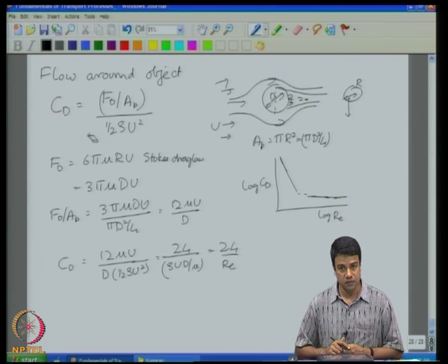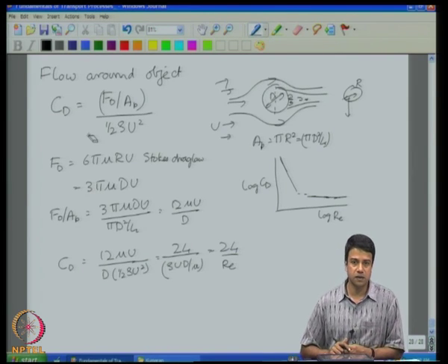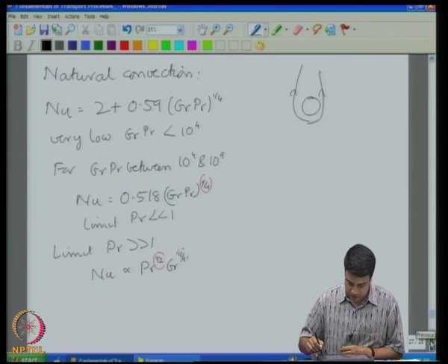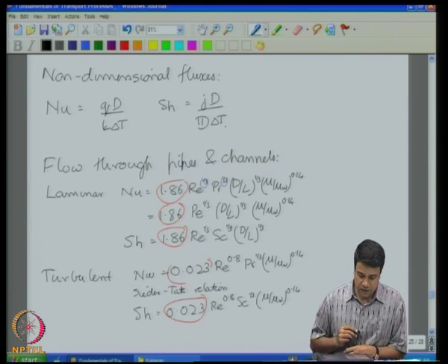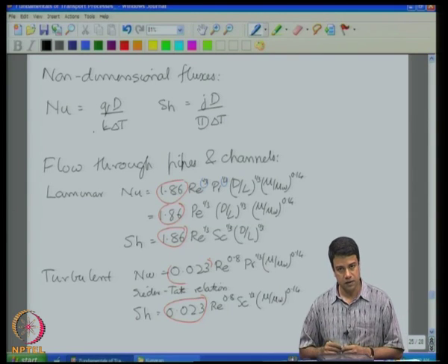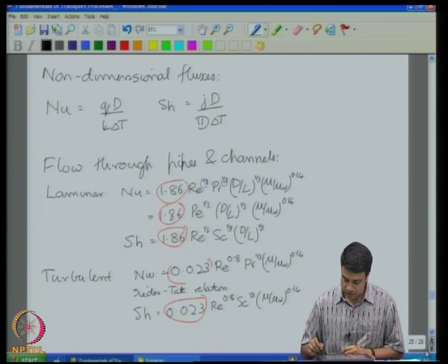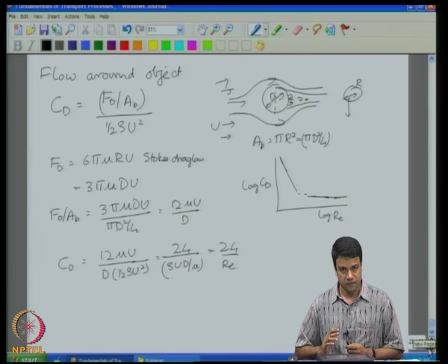I could very well have scaled this with the viscous scales. In mass and heat transfer, the non-dimensional stresses are defined with respect to viscous scales, so with respect to the diffusion coefficients. The non-dimensional mass flux is defined with respect to a diffusion coefficient. For heat flux, the non-dimensional flux is defined with respect to the diffusivity of heat. And that is traditional. Since diffusion is the obvious mechanism of transport, it is traditional to do that. Whereas, in the case of momentum flux alone, historically the flux has always been scaled by a convective scale.